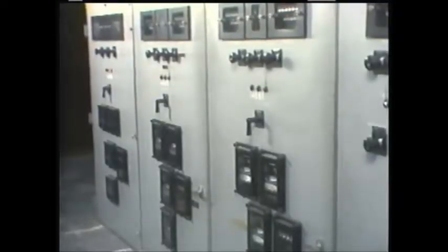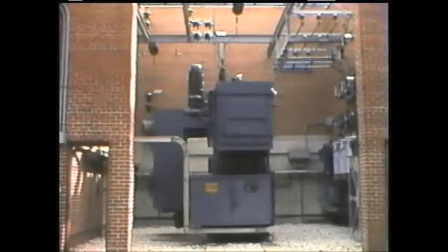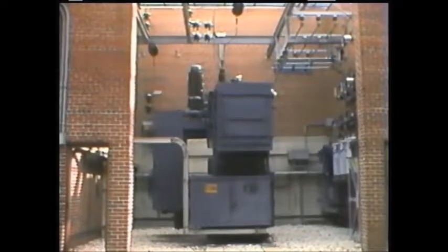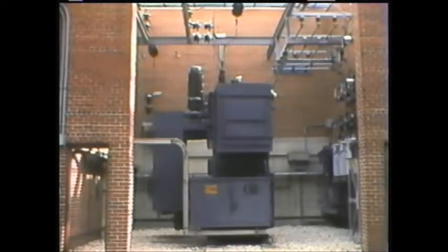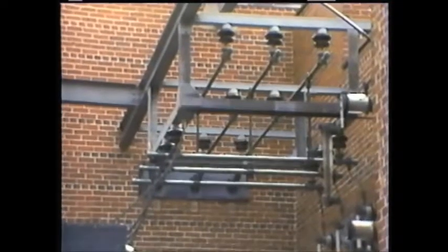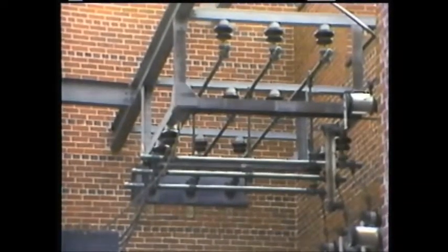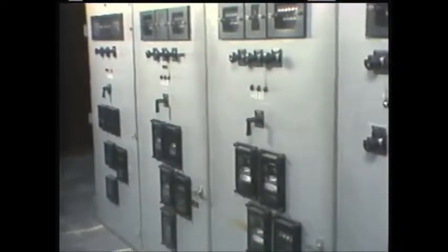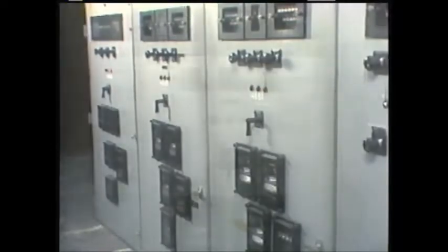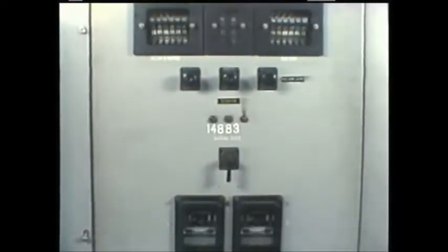For the most part, circuit breakers are located inside substations. As you'll recall from the last part of this program, transmission lines supply a substation with electricity. The transmission voltage is changed to distribution voltage by substation transformers that supply electricity to a substation bus. The substation bus then supplies electricity at primary distribution voltage to feeders. In many systems, circuit breakers are installed between the substation bus and the individual feeders. Generally, there is one circuit breaker for each feeder.